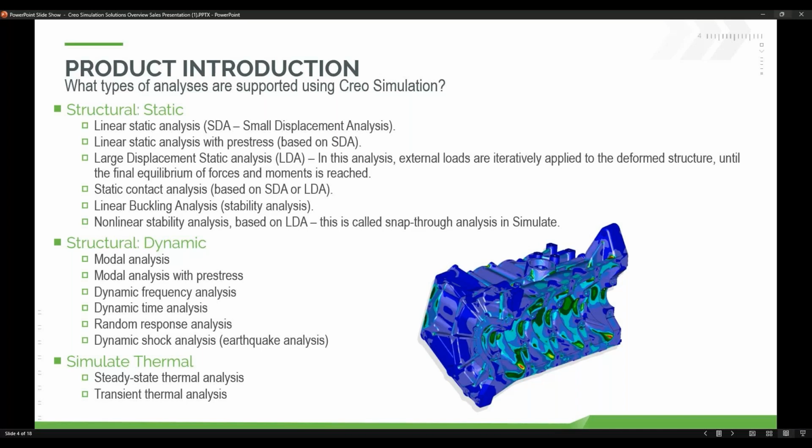We can do contact analysis. We can analyze where two objects would touch one another. So imagine you have a circuit breaker or a switch, and you flip that switch. The contact is going to actually touch the other end. We can determine the contact area, the contact pressure, and we can also apply slippage to that so that you can have your friction coefficients in there.